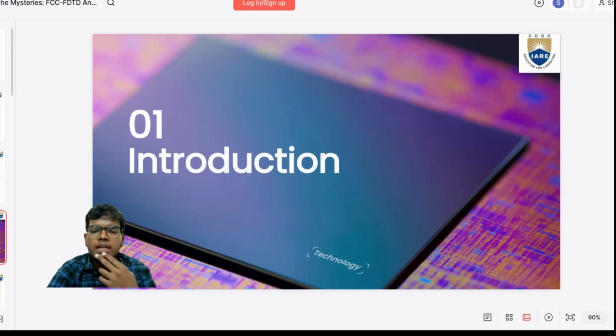Before moving further, let's briefly look at some basic concepts. Electromagnetic scattering happens when waves interact with an obstacle. A simple example is a metal sphere. When radar waves hit the sphere, the waves scatter in all directions. Now, if we add a plasma layer around the metal sphere, the situation changes. Plasma has unique electromagnetic properties that can alter the wave behavior, affecting reflection, absorption, and transmission.